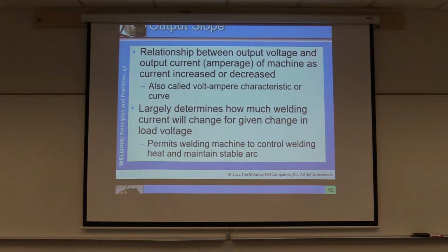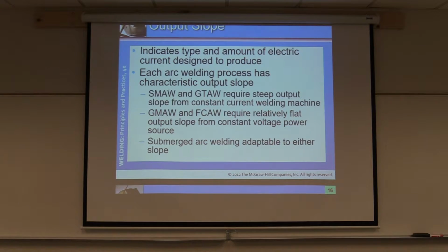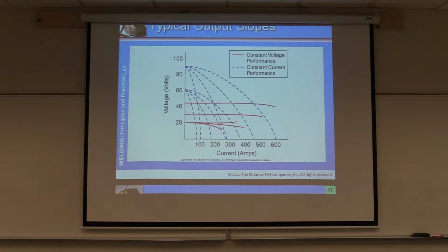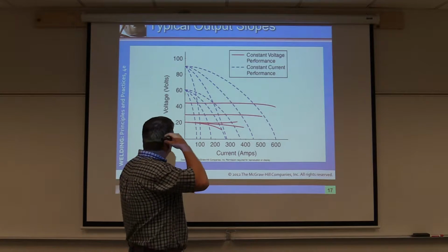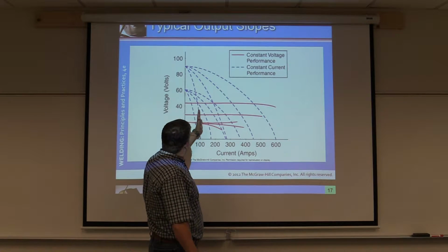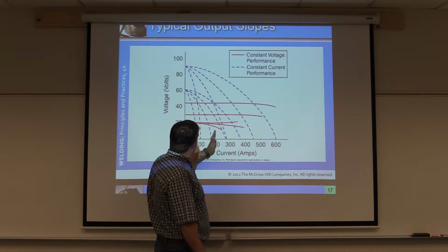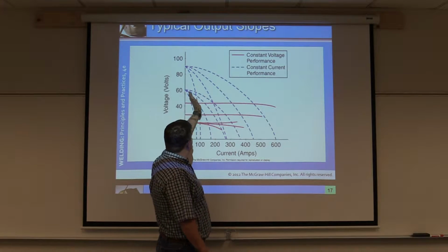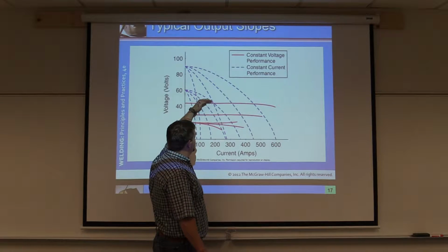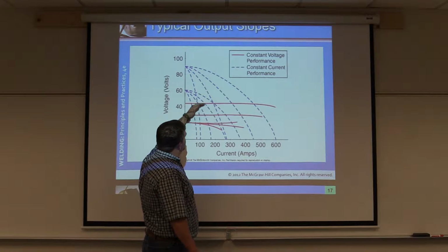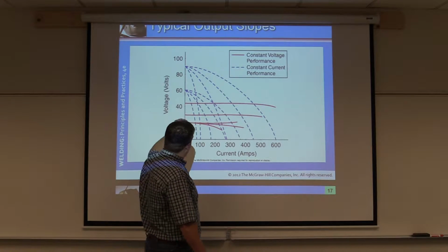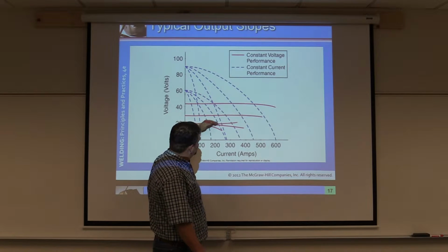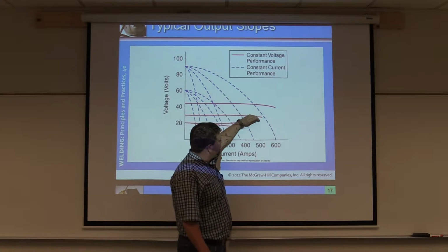So, it does show us this. Up here in this corner, it shows your constant current performance. So we're going to be reading it this direction. Again, it does fluctuate some, correct? The further away we get from the workpiece, it starts to drop off fairly drastically. This voltage is trying to maintain the same. So this is our constant voltage performance. See how it stays pretty well flat.